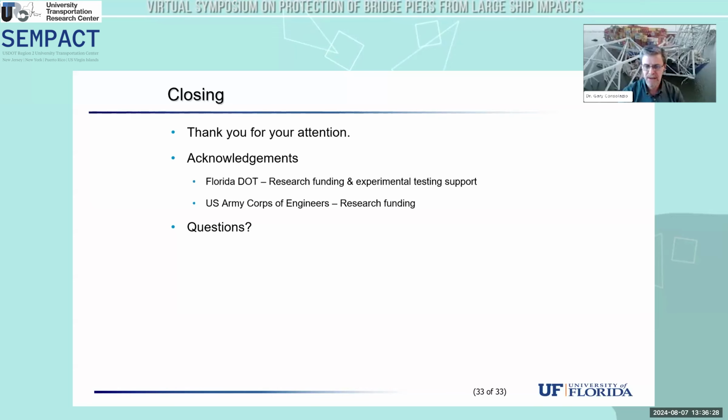When we did the St. George Island testing, we did look at different ways of also including mass contributions from the soil surrounding the piers. There was some influence on the stiffness of the soil as a result of the dynamic resistance of the soil. But within the greater context of other uncertainties in terms of impact conditions and so forth, we concluded that using a PY approach is generally adequate.